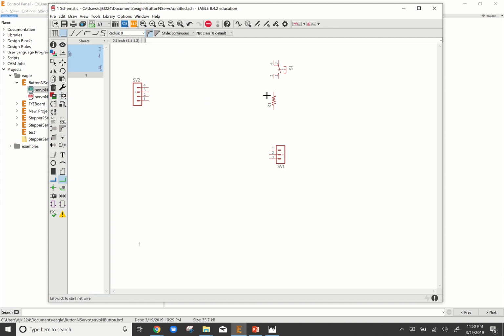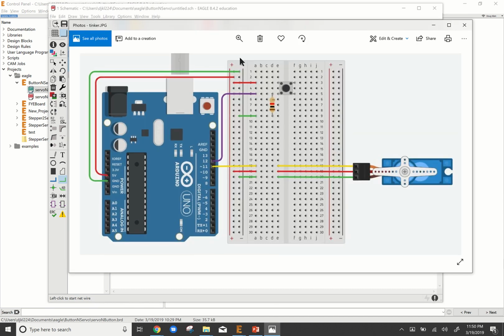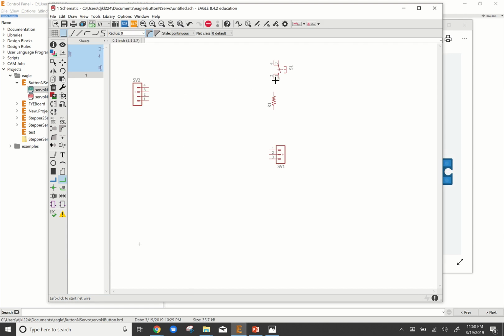With that accomplished, now I need to draw in my wires. And so I try to think of a way that allows me to set up the wires so that they don't cross. If they don't cross, I know that when I mill out the board, it's not going to have any shorts in it, right? And so I typically try to start with my more complex part. And so this row 5 here, where I have the button, the resistor, and the wire all going into the same row, and they're connected, is my more complex area. So I'm going to start with that.